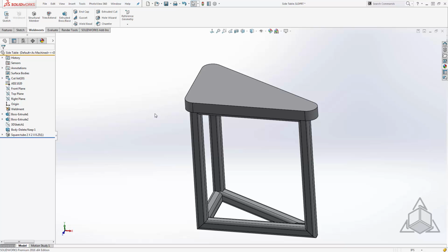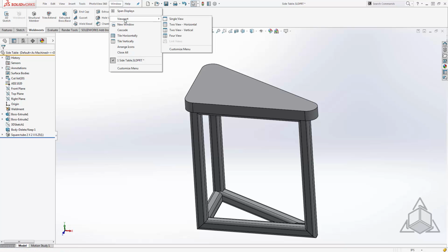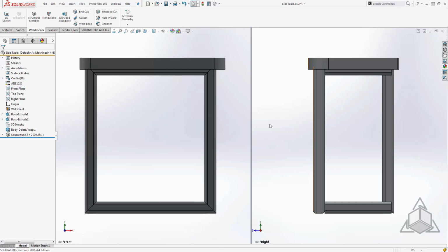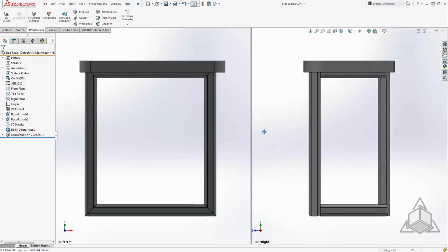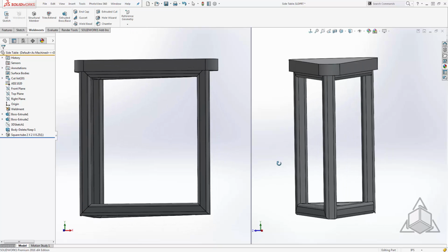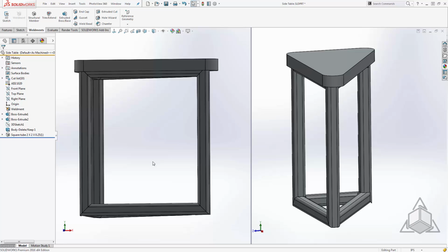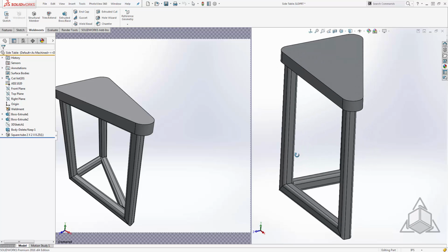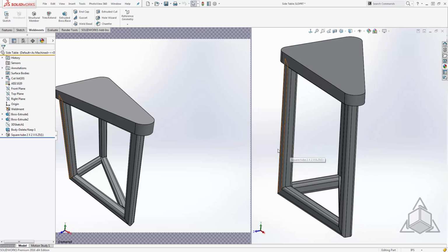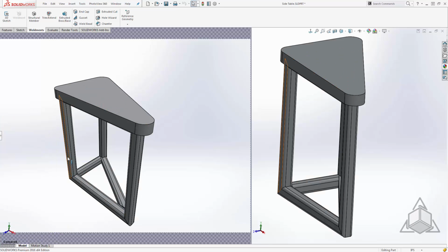So what I like to do is split my screens, and we can do that by going up to Window, Viewport, and set this to 2 view. Typically I go with 2 view vertical, so they're side by side. By default these two will move together, but we can unlink them. We can do this right from right clicking, or we can go back up to Window, and now you'll see that these will move independent of each other. So now on this side, we can go back and move into our camera view, and on this side we can continue working with the model. Now in 2016 we have Breadcrumbs, so we don't even need to access the tree as much as we used to. We can hide this away and really take advantage of the full real estate of your monitor.